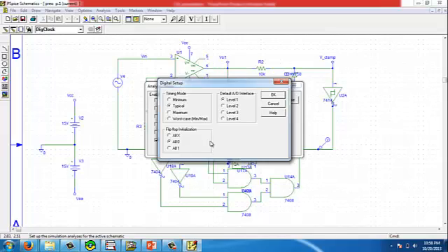Also, using minimum, maximum or typical allows signal propagation through digital devices to be represented as instantaneous transitions, while in case of worst case, the effect of individual component delay ranges are propagated throughout the circuit. The default A to D interface is level 1, which will strictly map logic levels onto changing input voltage. Level 2 is generally for A to D interface transitions directly from 0 to 1 and 1 to 0 without passing through any of the intermediate stages of rise time, fall time or unknown state.